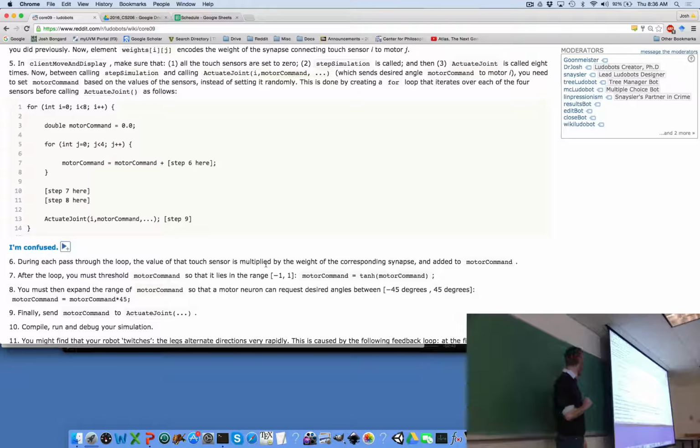And the reason why we do that is because we want to start with motor neuron 1, so i equals 0 in this case. We then are going to compute the value of the sensor neuron multiplied by the weight that connects sensor neuron 1 to motor 1. Do that multiplication. Then add to it sensor 2 times the weight that connects 2 to 1, plus the weight of 3 that connects 3 to 1, and so on and so forth, right? Which is what's going on right in here. We're doing that multiplication here, and we're summing it over the 4 sensor values that are influencing motor 1.